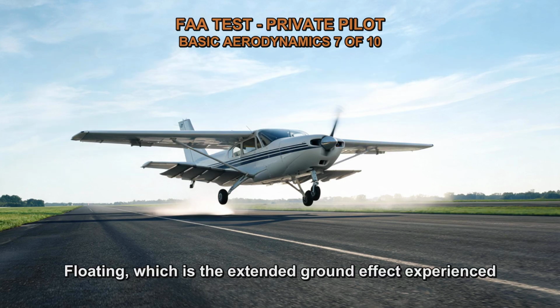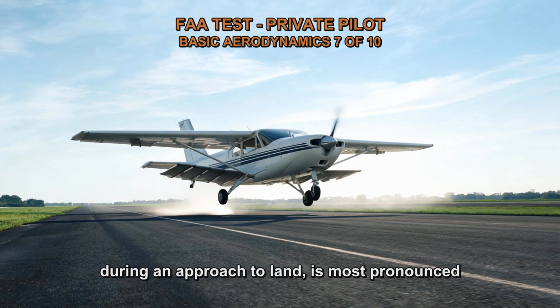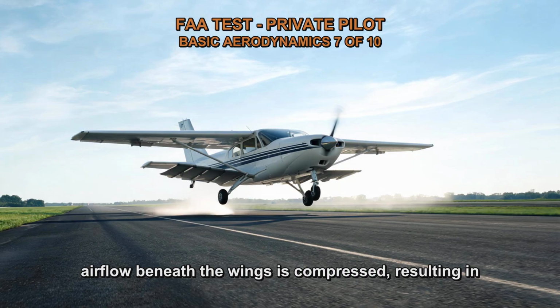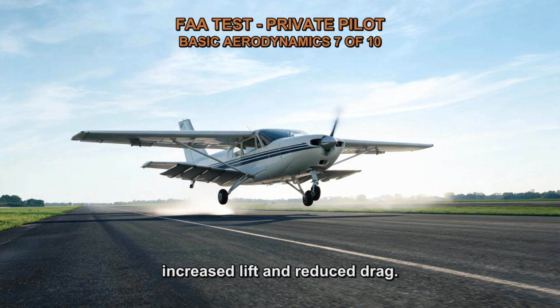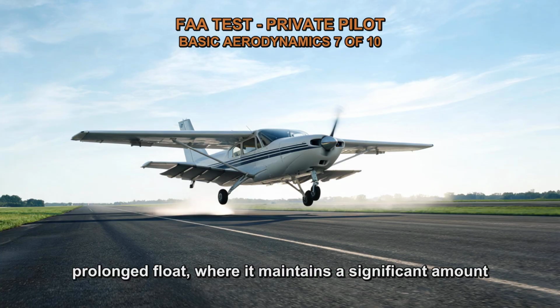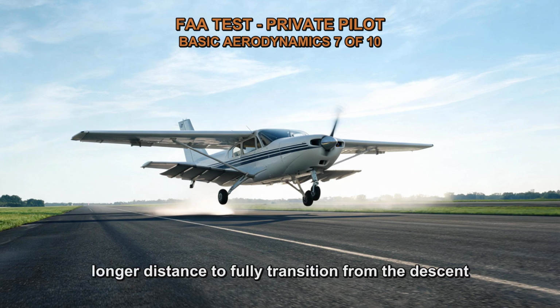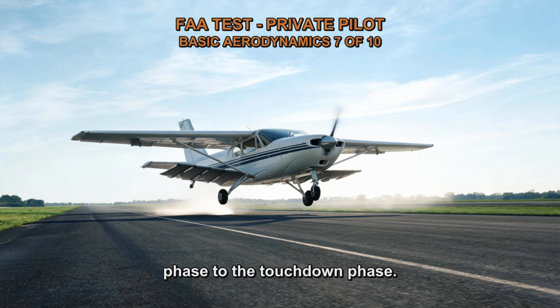Floating, which is the extended ground effect experienced during an approach to land, is most pronounced when the aircraft is flying at a height of less than the length of the wingspan above the surface. When the aircraft is in ground effect, the airflow beneath the wings is compressed, resulting in increased lift and reduced drag. This can cause the aircraft to have a prolonged float, where it maintains a significant amount of lift even at lower airspeeds. As a result, the aircraft may require a longer distance to fully transition from the descent phase to the touchdown phase.